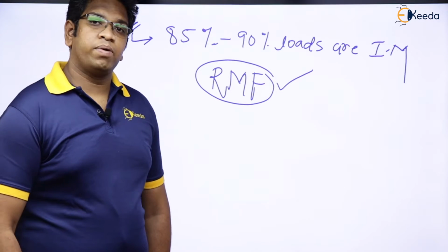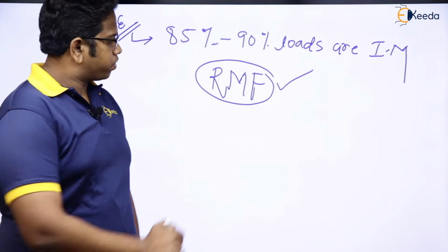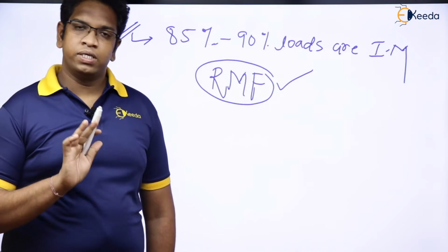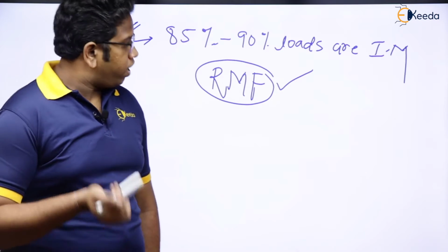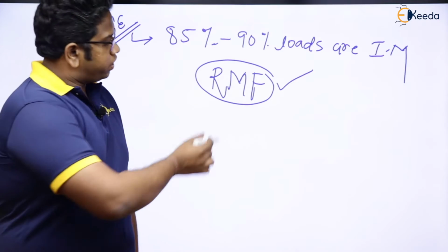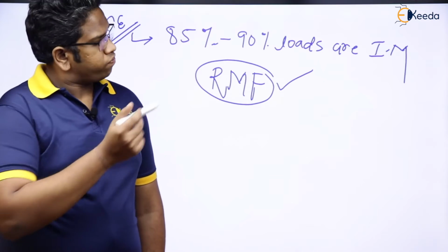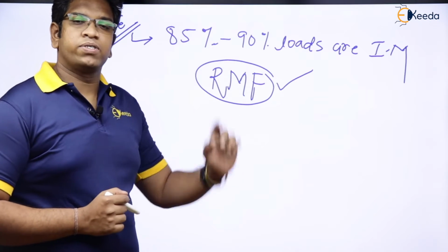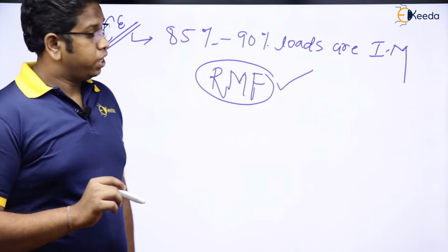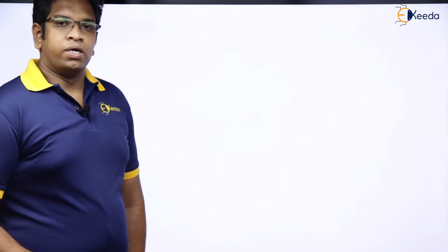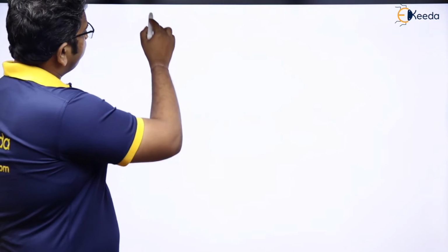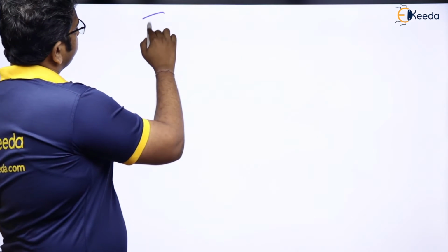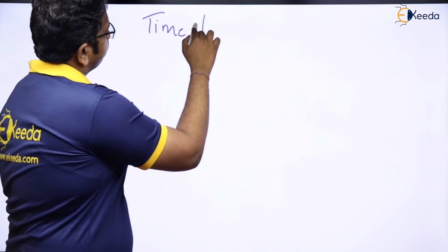So for electrical people, we love sinusoids because the rotating magnetic field will be best when it is a sinusoid. That is the only reason. And why are we so interested in the RMF? Because of induction motors, 85 to 90% of the loads are induction motors. Anyways, see here. Now, we had talked about time to space earlier.